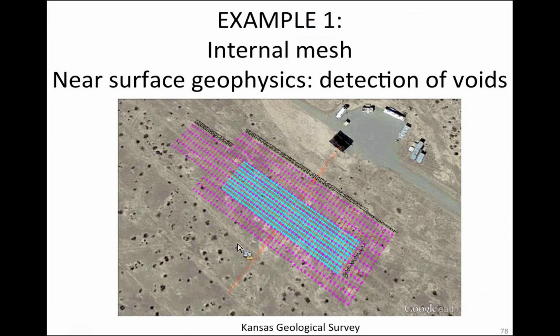If we want to detect, using SPECFEM and joint seismic imaging, the voids, we know a priori the tunnel should be about in this area, about 10 meters depth, and the size of the tunnel is like 1 by 2 meters.